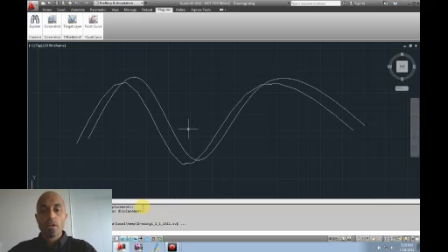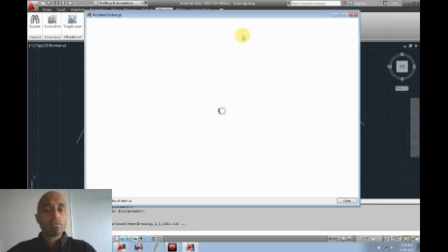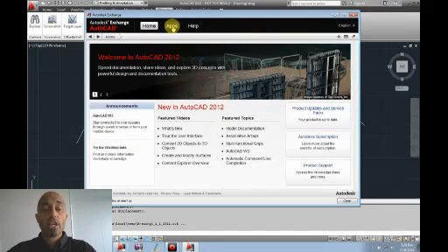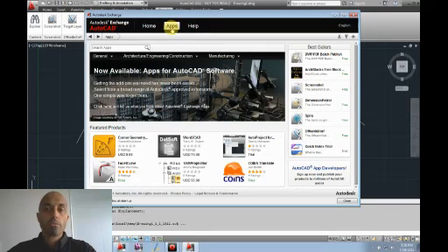The CUI command allows you to manipulate the ribbon, toolbars, and other graphical user interface components inside AutoCAD. Very, very useful, and you can get a lot of headway from customizing AutoCAD in that way. For external applications, if you're on base AutoCAD 2012, go check out the Exchange Store for AutoCAD 2012, and do expect more of these in the future.